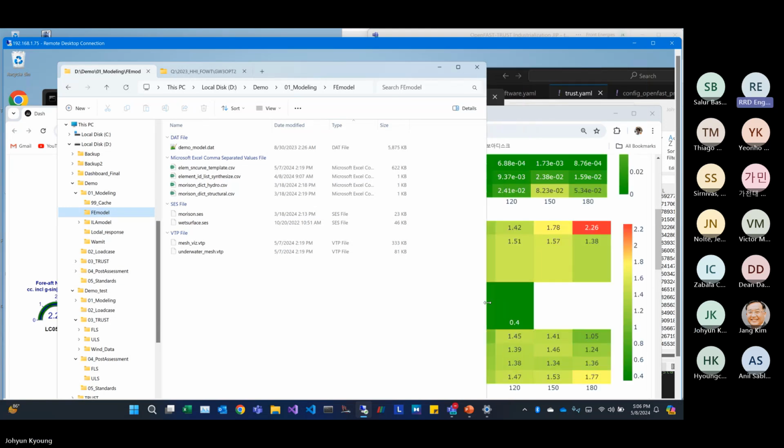Got it. Thank you. So are you getting the surface elevation as an input that gets passed to WAMIT, time step by time step? No, not step by step. This is a linear pressure mapping. Below the mean water level, the pressure mapping is pre-processed.